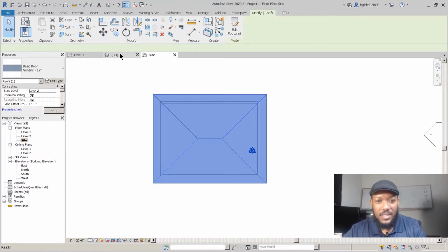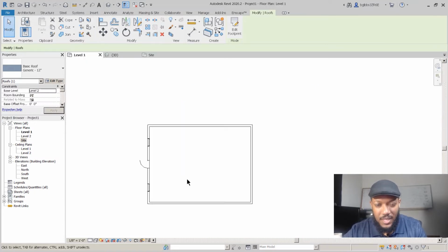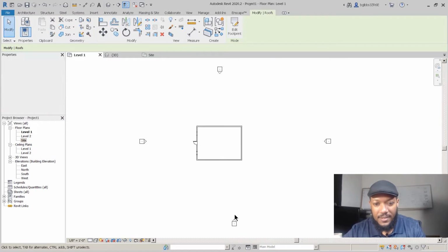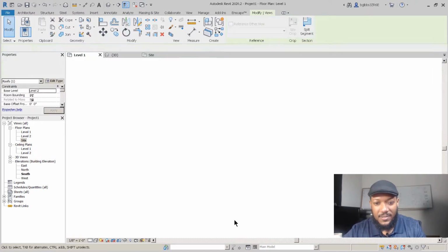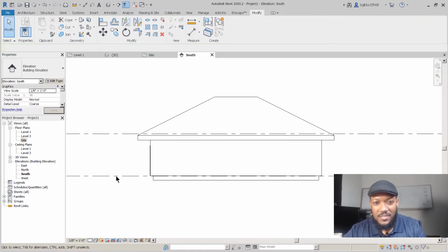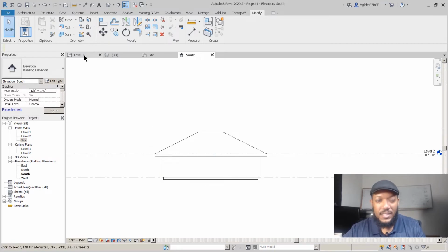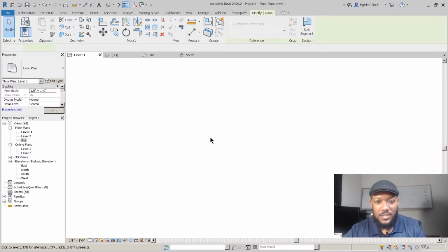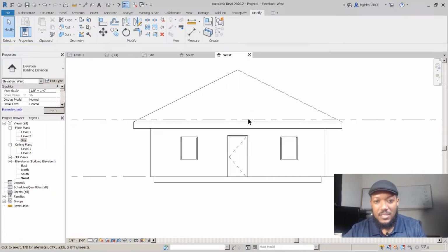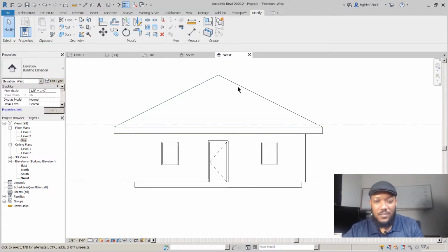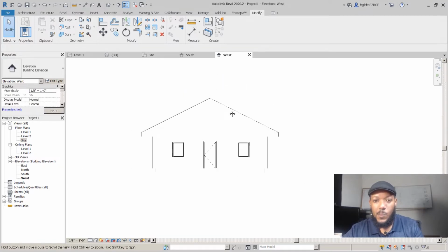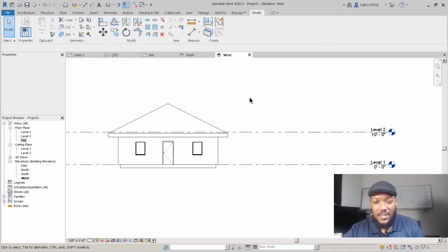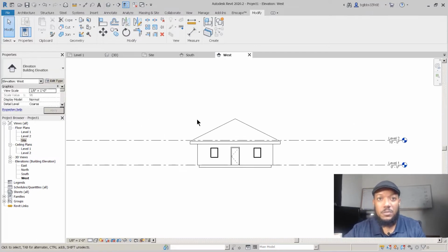Okay, now let's look at our view in an elevation. So the elevations are also in the level 1 plan. All we do is double click on the triangle, and we see our view. Now we click again, and if we click another one, the same thing happens. So you've seen that we've made a 6/12 roof, and that we've added these little items in, and it was just very simple, just from a few clicks.